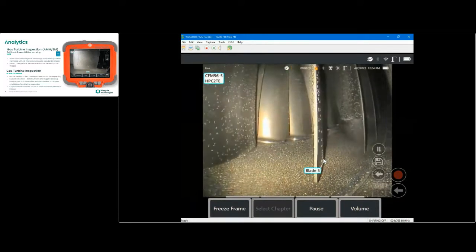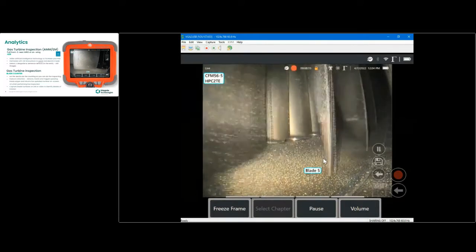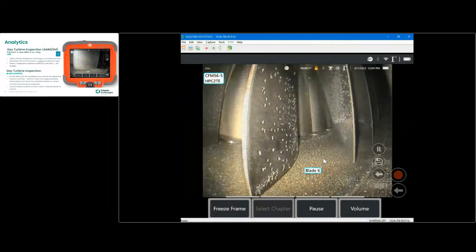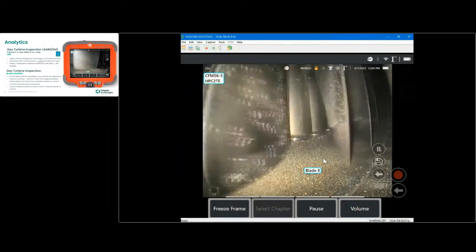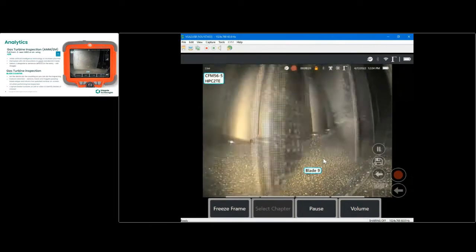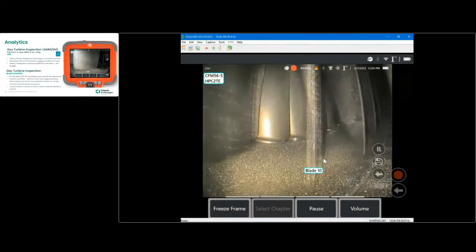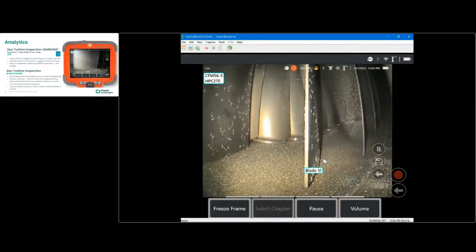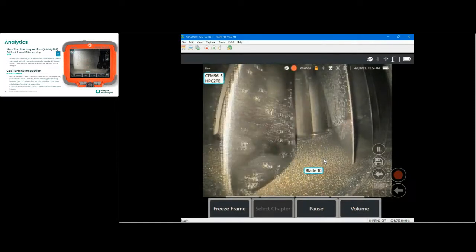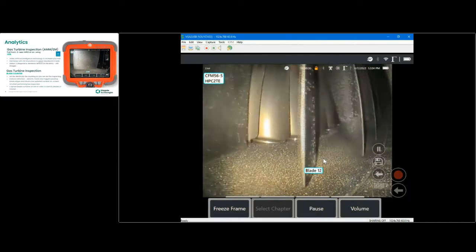So giving you a range of different views in this stage, in this particular case, quite an acute angle that most of you will be familiar with, associated with the inspection of, in this case, an HP compressor stage. It's very difficult to control the speed and position of the rotor if you're performing manual turning as opposed to using an electronic turning tool.